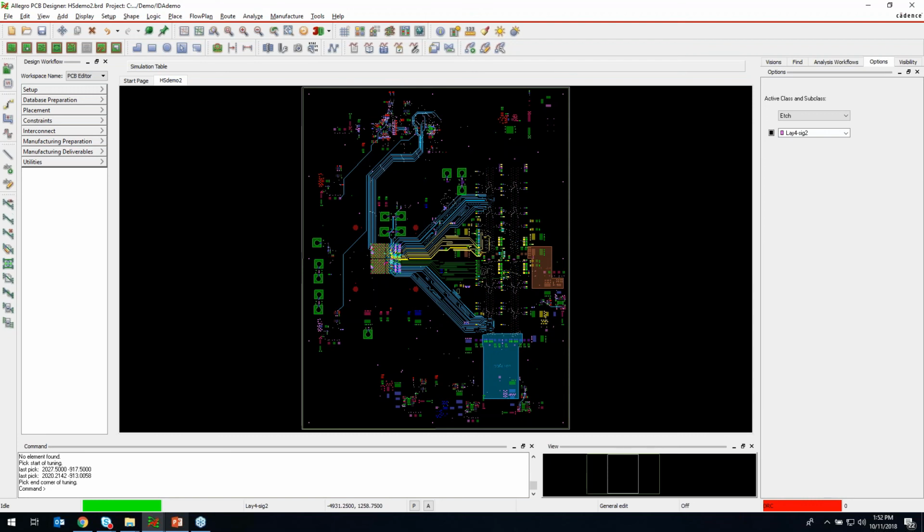Good to know. And would the program typically flag impedance mismatch of signals crossing split grounds, and would it take into account stitching caps? Yes, it does. So as soon as you cross a void, basically if you have impedance constraints set up, when you cross that void, you should see some type of reflection regarding how that void crossing is affecting the impedance value there. What was the secondary question on that? Would it take into account stitching caps?